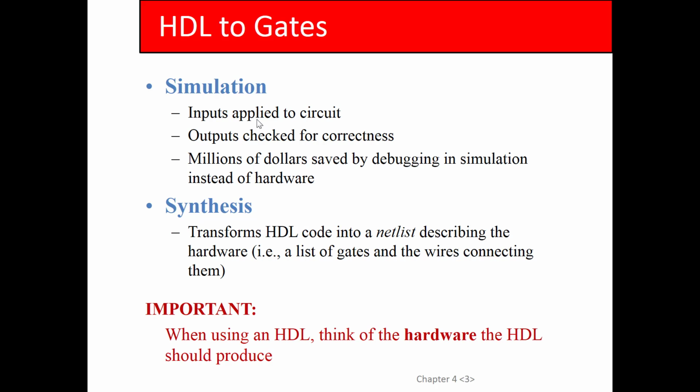Okay. Now there's two challenges with learning HDL. One is that it uses concurrent semantics because hardware is concurrent. There's no notion of a program counter or a line of code that's currently being executed. So all lines execute at the same time. The way you can think of it is everything's triggered by something. Every output that's set by a line of code is triggered by one of its inputs changing. Does that make sense? So you have to change the way you visualize how these programs are executed, because they're not really programs, they're hardware descriptions.